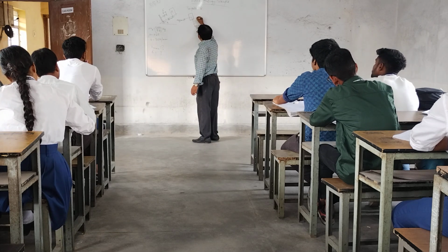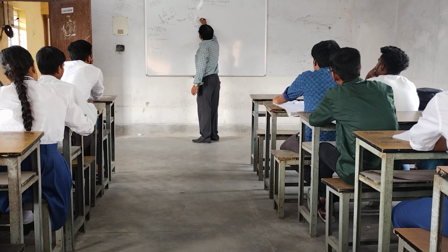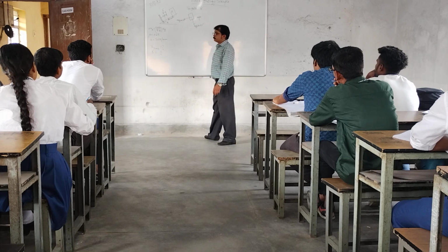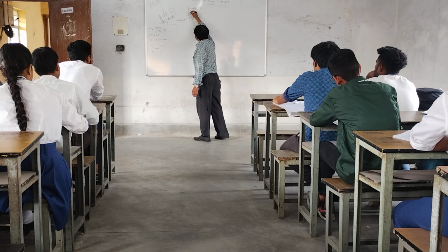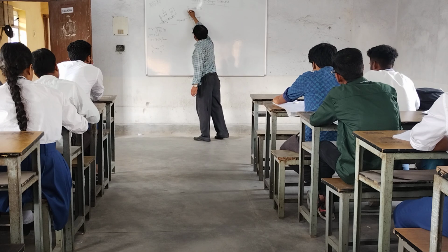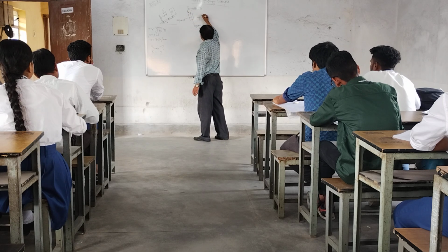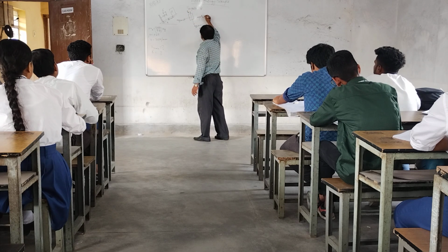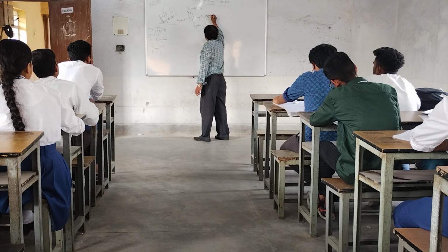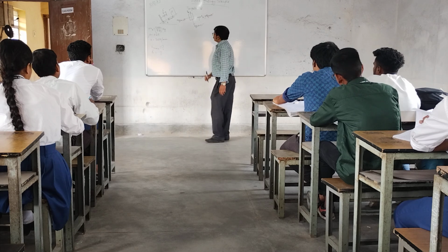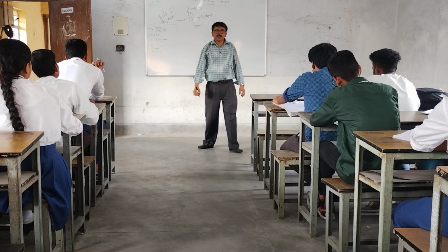After that, it is sliding down, so here is a frictional force, that is mu into the reaction force R_A. So mu into R_A, that is mu into M_A g cos 45. This is the frictional force. Any other force?